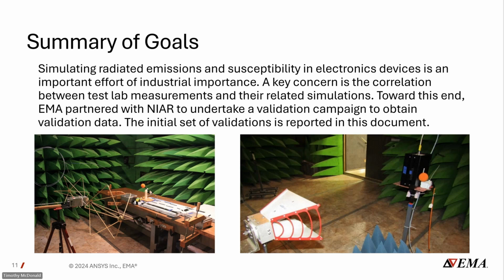So further, for models of PCBs and cables, it is important to be able to accurately represent how they radiate when excited by a source. So that's the radiated emissions. And then also to understand how they react when placed within an external electromagnetic field. So that's the radiated susceptibility we'll be measuring.